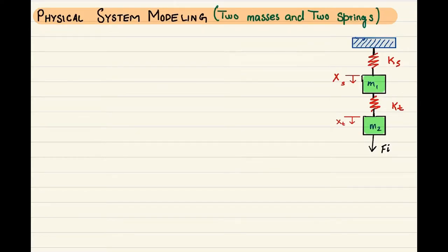It's a little bit more complex than the videos that we have covered before, but the method is going to be exactly the same to draw the block diagram. For the block diagram, we have to first go for the free body diagram and then derive the equations for the total net force applying on M1 and M2, and then according to those equations we are going to draw our block diagram.